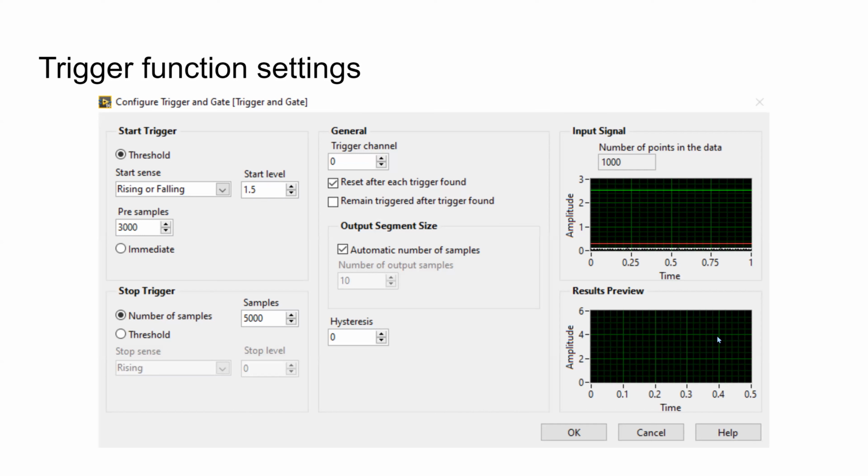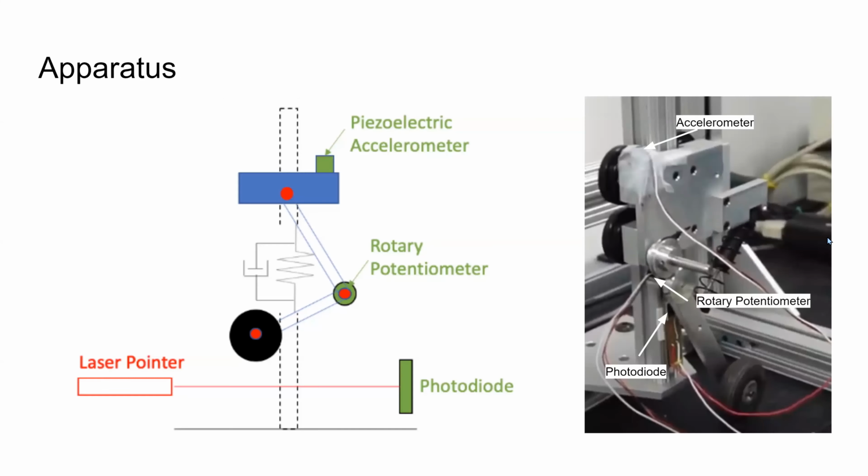We basically shot a laser at the mirror and we got a value for that reading, and then we got a value of the voltage when the laser was not on, and basically the mean value between those two is the trigger point that we used, and that's basically the most important thing here.